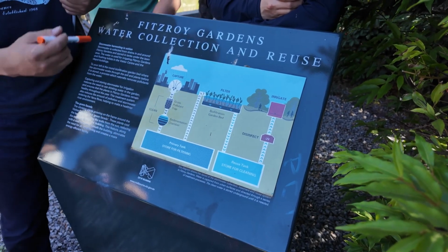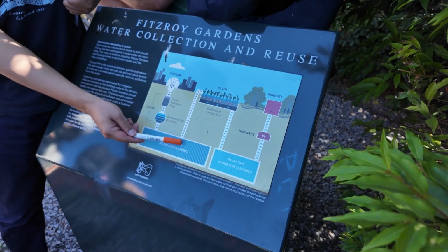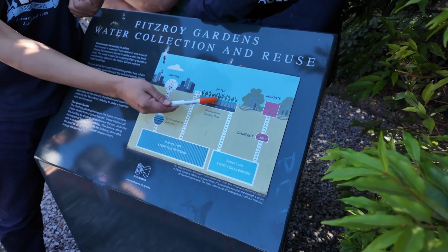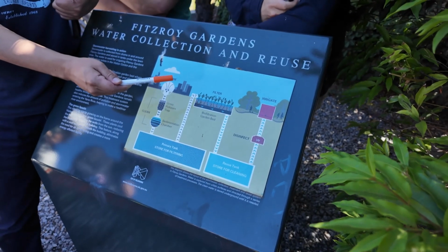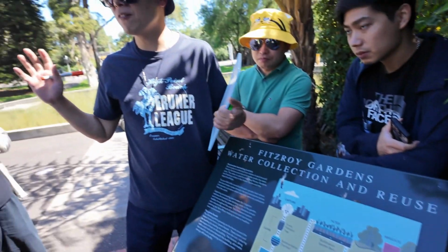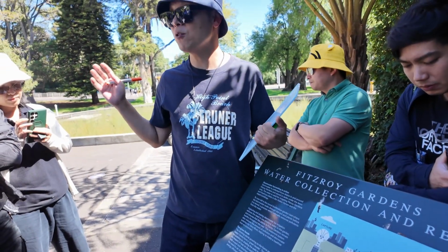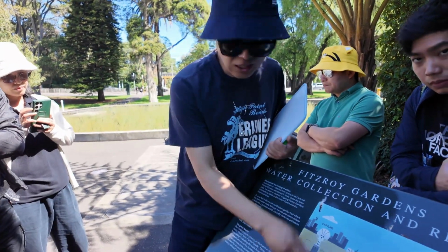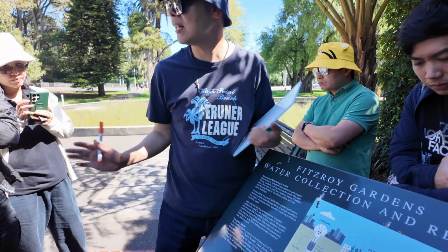And then once the rain has passed, when we need water, we take this water and pump it into this bioretention system. So how much we pump depends on demand. Let's say we need 2 cubic meters a day for the next day. Then that's how much we pump. We don't pump more than that.